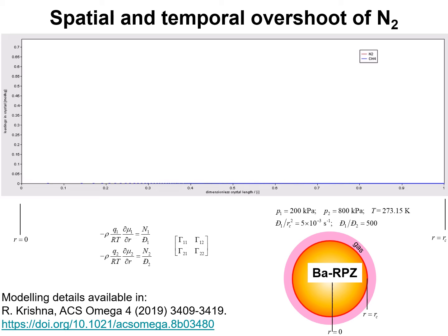The key to kinetic separations is to terminate the diffusion process and the contact time such that the component loadings within the particle correspond to the conditions during the earlier transients, and this results in significantly higher amounts of nitrogen within the particle as compared to methane.